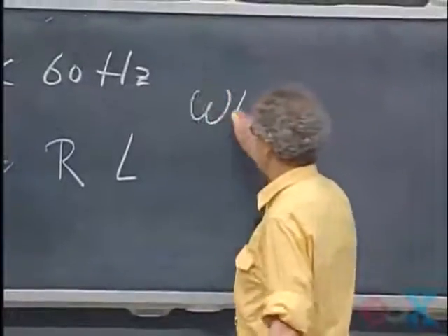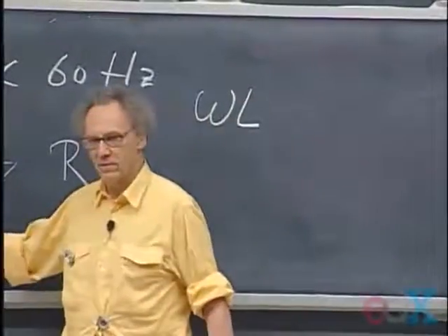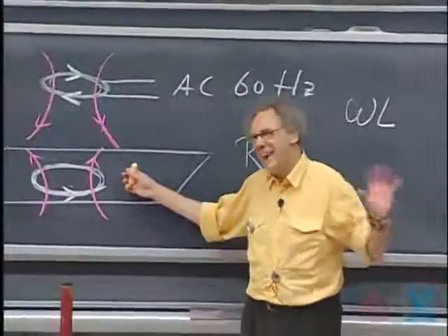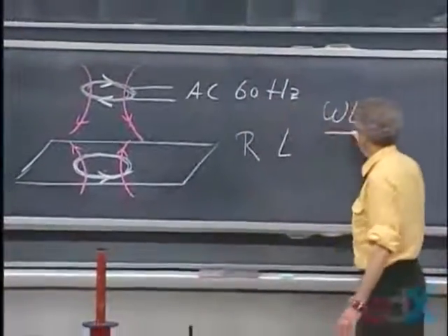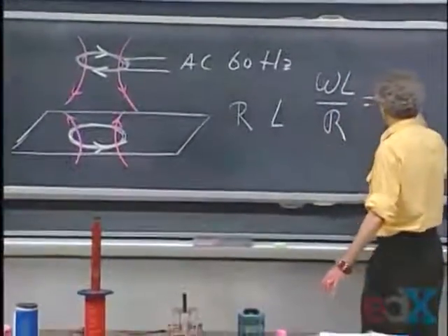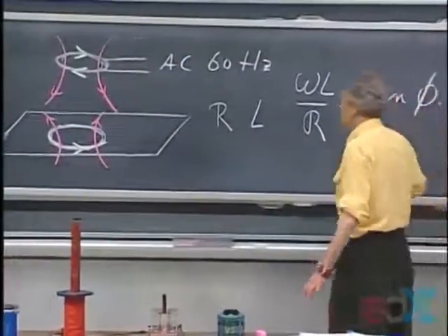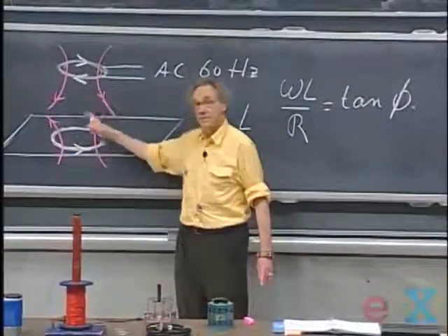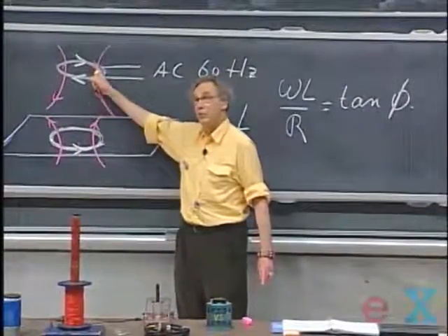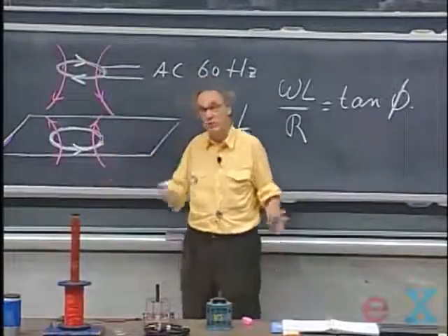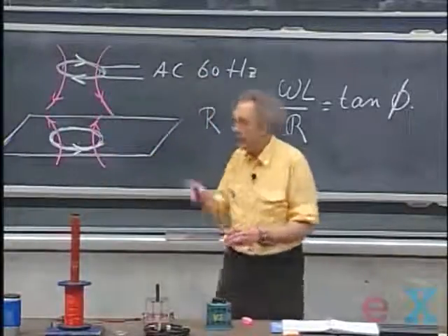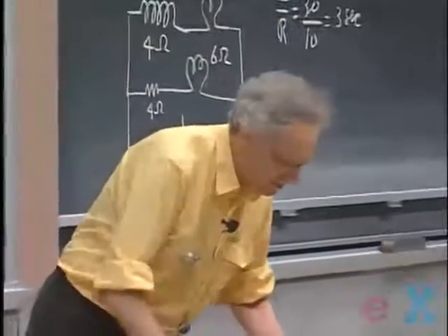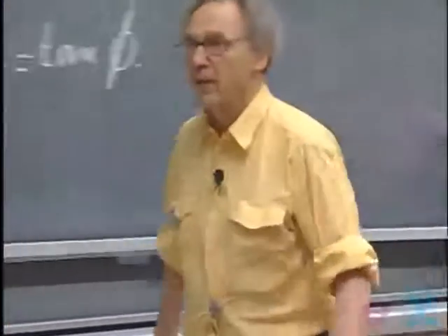And so we do get, in this conductor, the induced current delayed by a phase angle given by this equation, delayed over the induced EMF. The EMF is immediately coupled to what this coil is doing, but the induced current is delayed. And I have something that will allow you to see that perhaps in even more detail.